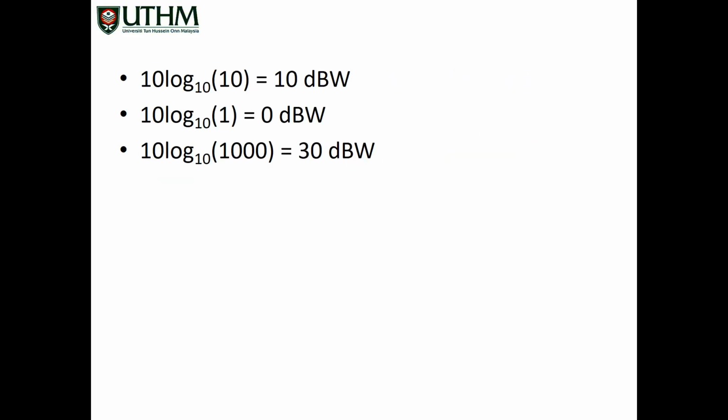So 10 log 10, you get 10 dBW. 10 log 1, 0 dBW. And 10 log 1000, you get 30. But this one is in terms of dBW.